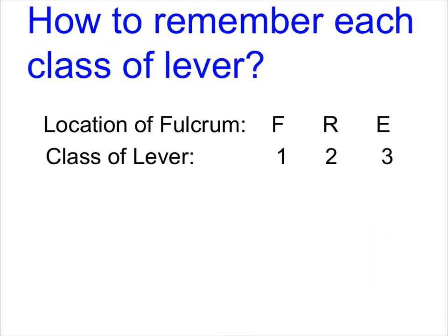So I wrote this slide a couple years ago when a student came up with a clever way to remember each class of lever. So for a first class lever, the fulcrum's in the middle. In a second class lever, the resistance is in the middle. In a third class lever, your effort force is always in the middle. So FRE: 1, 2, 3.